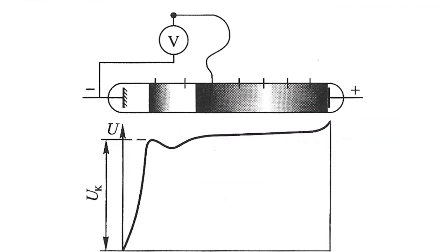A characteristic feature of the glow discharge is the spatial potential distribution along the tube's length. Almost all potential drops in the discharge occur in the cathode dark space. Such difference of potentials between the cathode and glow discharge boundary is called the cathode potential drop. It is the major property of the glow discharge which distinguishes it from all other forms of gas discharge. The cathode potential drop depends solely on the cathode material and type of gas. It is proportional to electronic work function of the cathode.